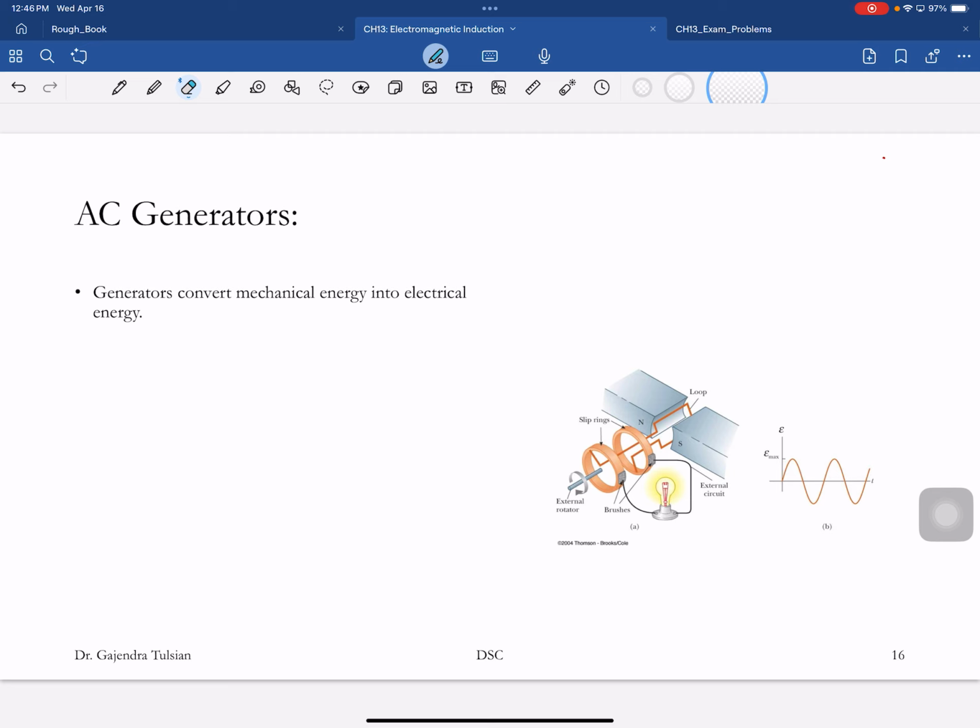Okay. All right, so like I said, the EMF induced will come with the negative sign, d by dt of B A cosine theta. And what we are doing is, here's the A vector, the magnetic field is like that, there is theta, and as I said, theta is the easiest to change in practice. What you do is you rotate this coil, and that'll induce an EMF. And if this coil is hooked up to the outside world like so, what you get is an AC voltage.